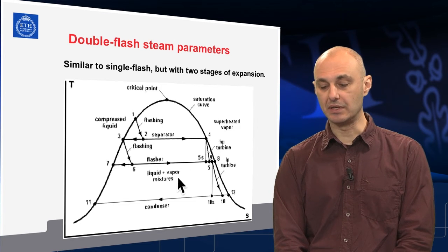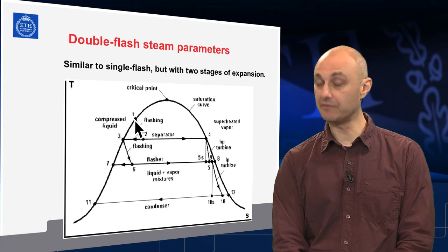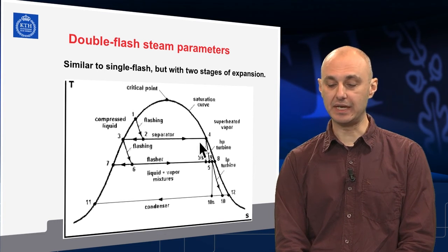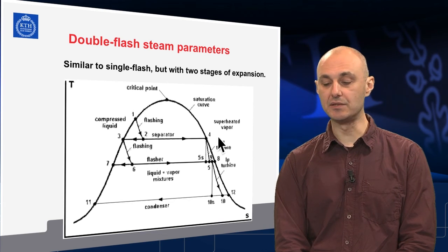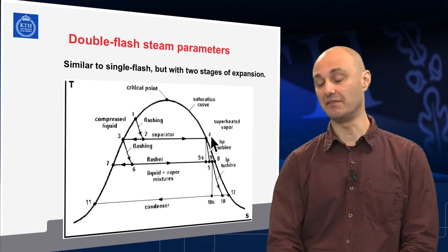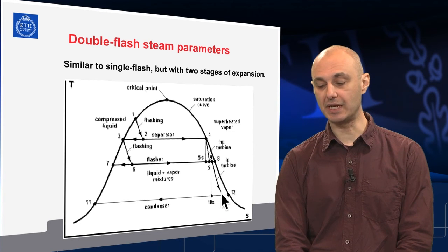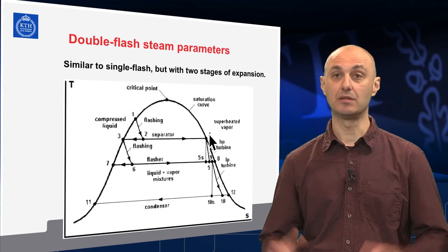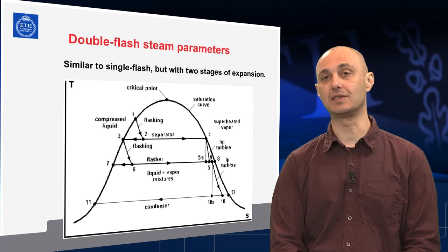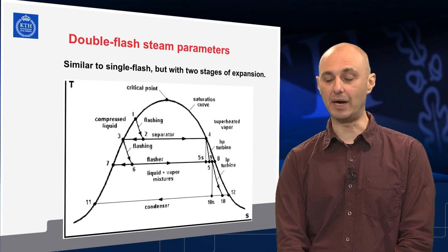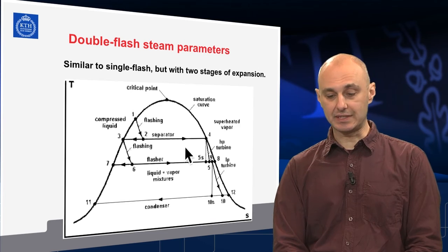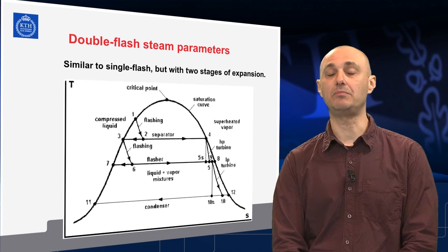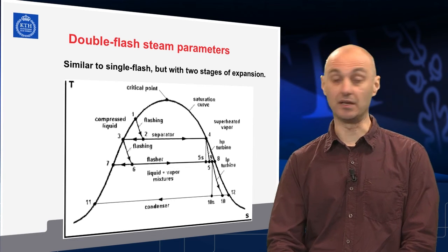The optimization here is that if we had, starting from the same input condition, one single flash will provide a certain power output, but if we divide it in two, and why not even more, 3 flash steps, we can actually generate much better mass flows, or higher mass flows of steam, totally summed for the different flashing steps, thus generating a bit more power. A third flash step can be added and has been attempted in only a few power plants. It is then difficult to justify economically.